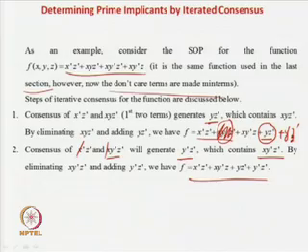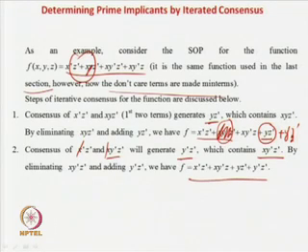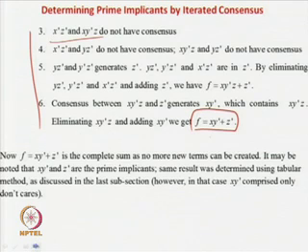This is what we started with, and we have never opened it up into its canonical form. We started with this one, tried this two-pair, generated a new term and eliminated this, then tried with this one and found a new term and eliminated this. We keep doing it and finally get this expression, which has only the prime implicants. As we have not blown it up, the complexity is much lower than the tabular method, which started off with a full exponential blow up.